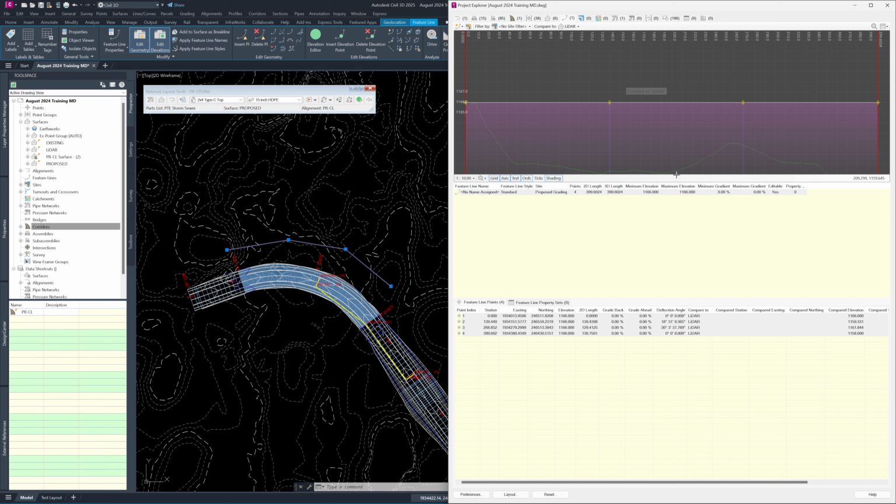It drops down through there, and it also shows your elevation out through there. So it helps to, let me zoom out a little bit, there we go. So this way you can say, okay, if this was a wall, I need this wall to be at a certain elevation. How does that compare? Am I close to matching existing grade? Over here I am, over there not so much. You can start throwing in some extra points, vertices, and adjust the elevations appropriately.